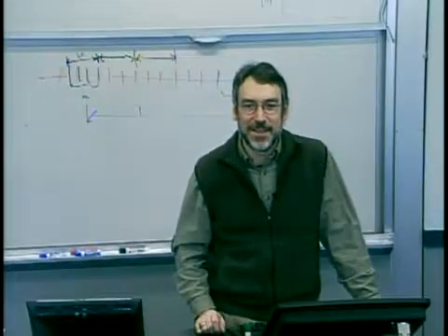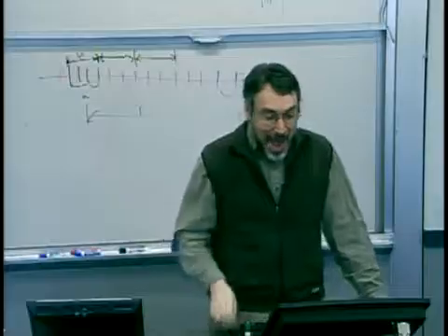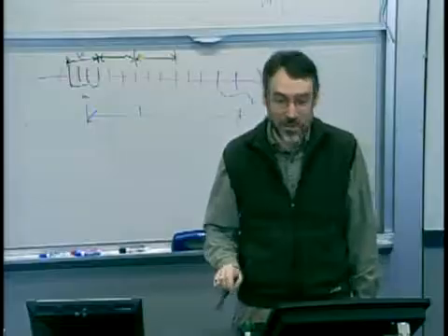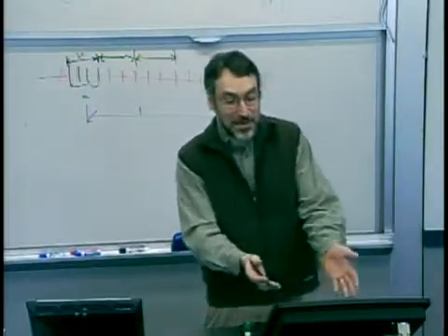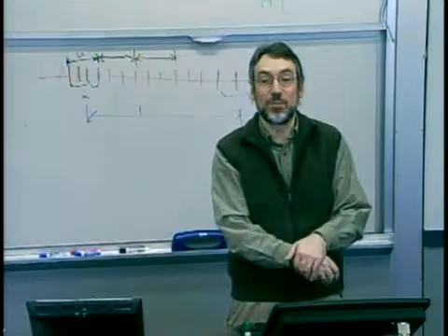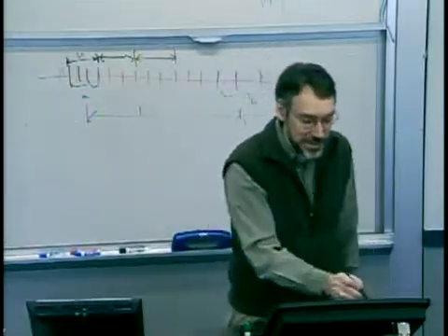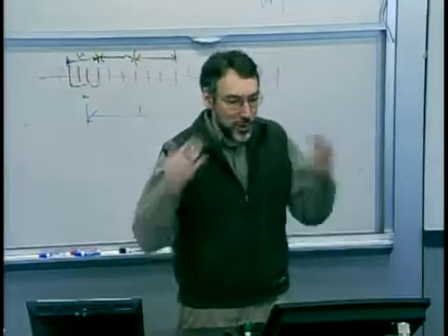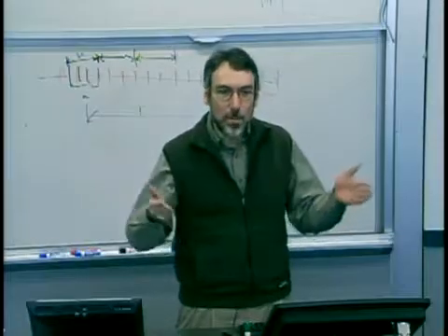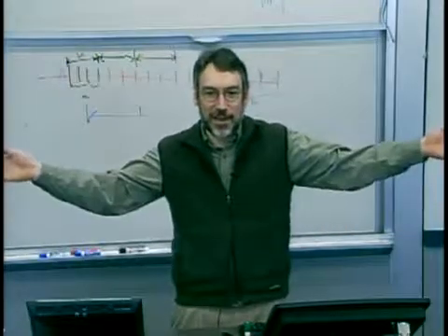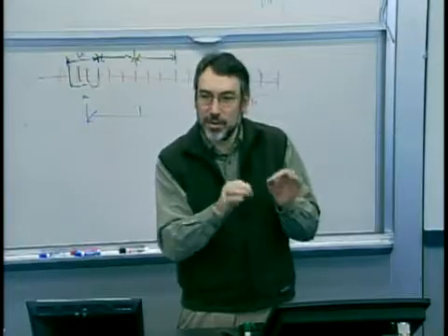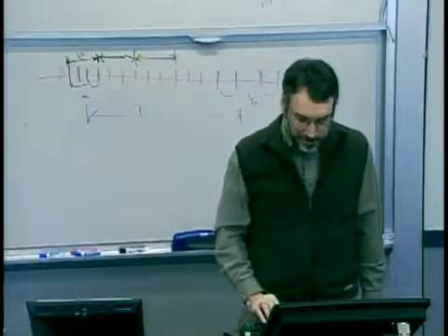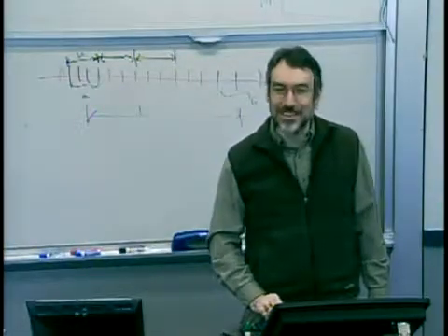Wouldn't it normally be safe to say that you want your spec limits outside your control limits? Absolutely. Here you're having a huge fraction of non-conforming. That's my point. Your spec limits may be very tight, and your process would be horrible. This is not a capable process. So normally, yes. What you normally want to do is trigger on alarms much before you have parts falling outside of spec, so that you can react to drifts in the process before they cause you disaster. Absolutely. That was implicit. I'm glad you made it explicit.